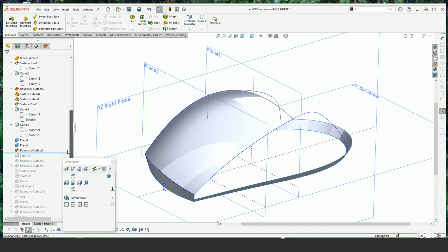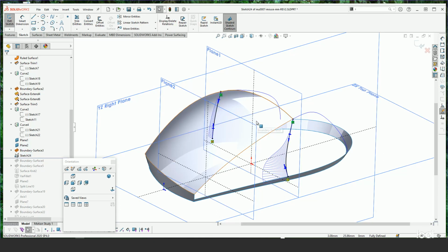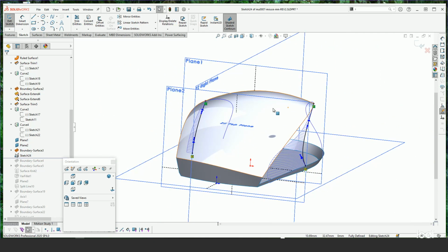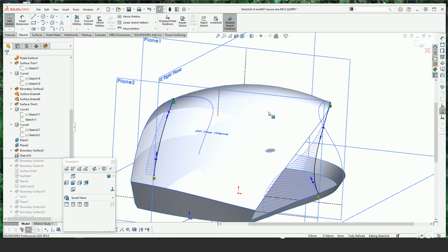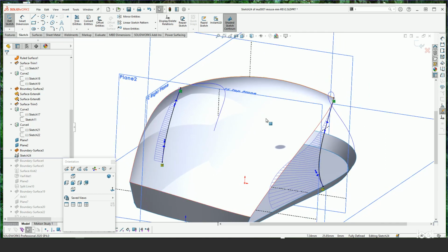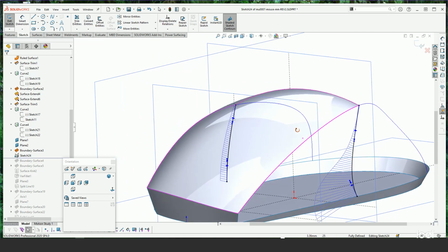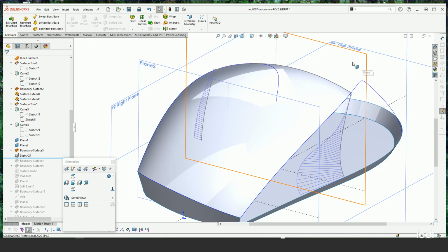So before I do that, I need to actually establish a boundary midway through for those side surfaces. On that same plane, I've created a sketch with these simple 2-point splines, and looking at my model and measuring and doing cross sections with the physical mouse through these areas, I've established these curves. Again, 2-point splines, turned on curvature so I can see that I'm getting a good continuous transition both on the left and the right where this scallop is. And then with those, we can then go ahead and create our left and right boundary surfaces.